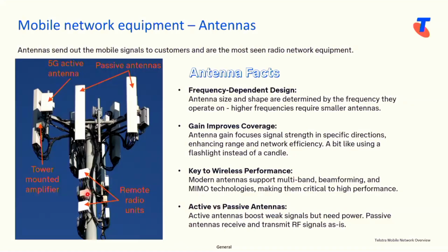but it does come with a maintenance risk. I should have explained this box here in the middle is like a distribution box. So we're having a fibre going up to these radio units, and you can see there's two there on this sector, and this box is splitting the fibres to these two separate radios. Also, we need power up there, so that fibre cable is laid up with copper cable, all in one cable, and so it's carrying, I think, a DC 48 volt, running up to these units.